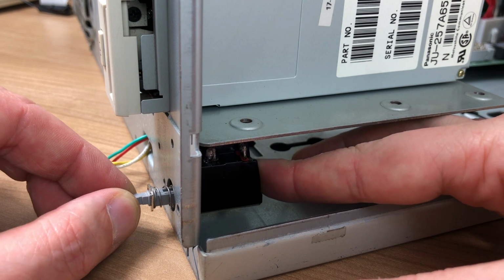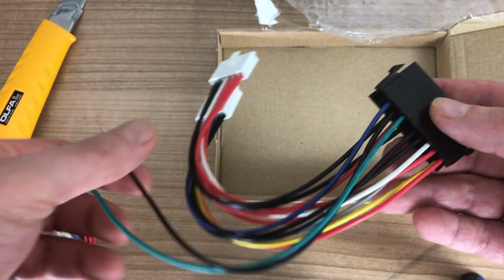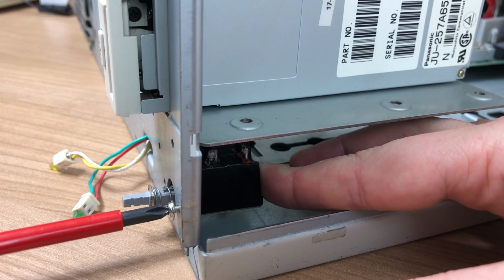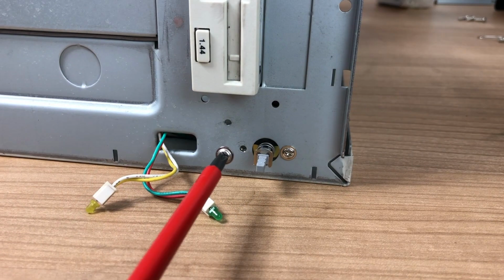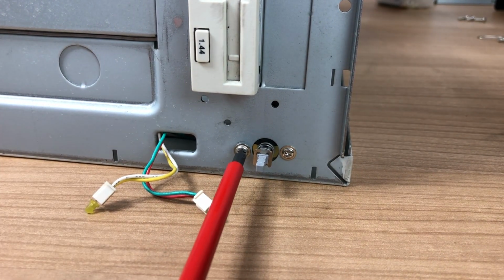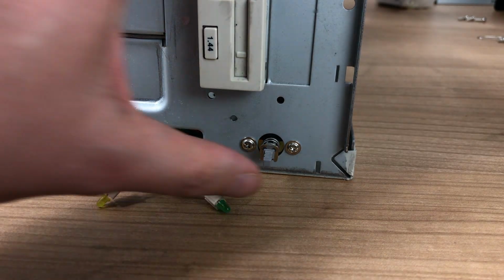On an ATX power supply, once you've already converted into DC, you only need to bridge 2 contacts on the ATX connector itself. So what we're going to be doing here is we're going to be using our button. We're going to attach it to the case and hook it up to the ATX power supply connector.